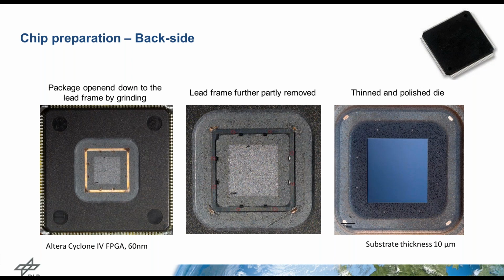It's required in our case because, as you can see here, silicon is not transparent for visible light. In a photo taken with visible light, you can't see through the silicon substrate. And this also explains why we have to use wavelengths for lasers and others in the near infrared region. But this is what we have to do, and when we have this, we can start.